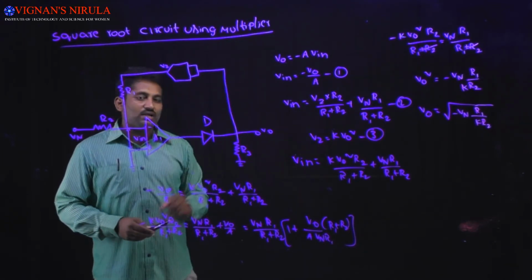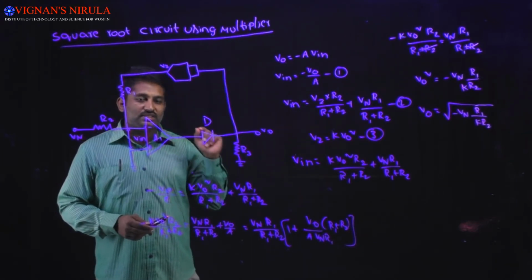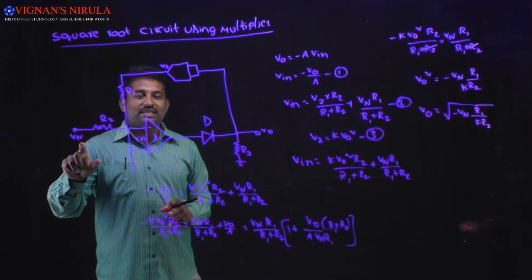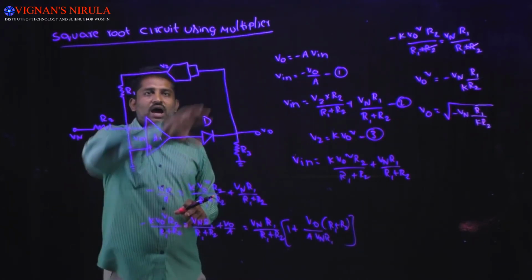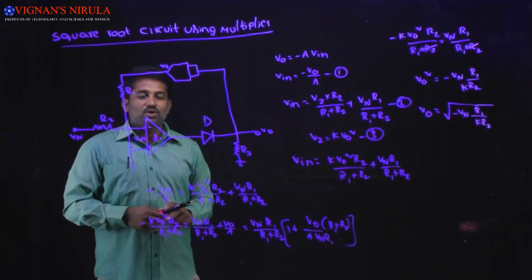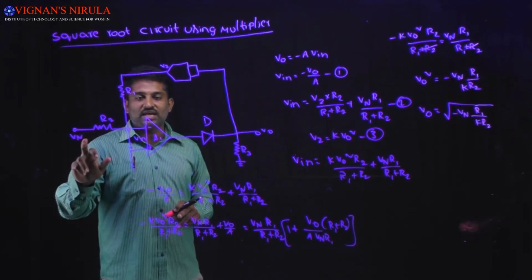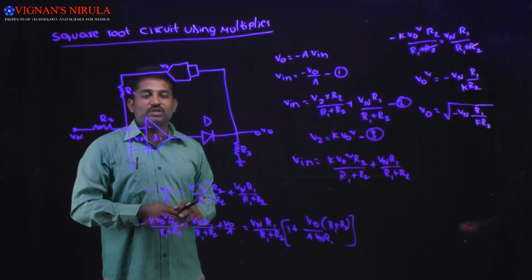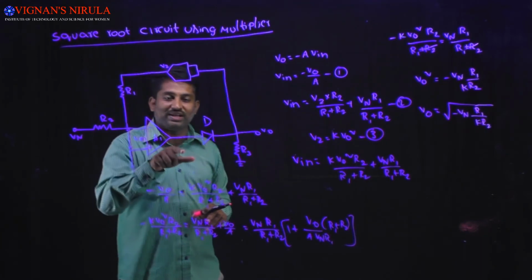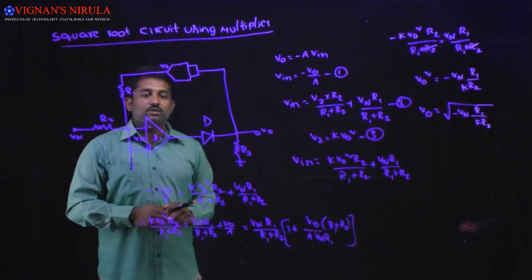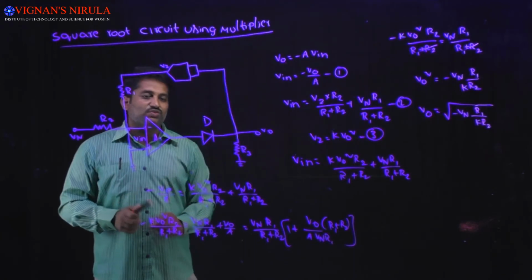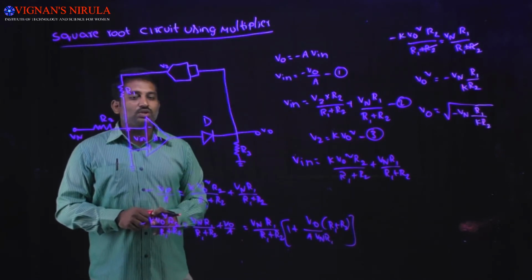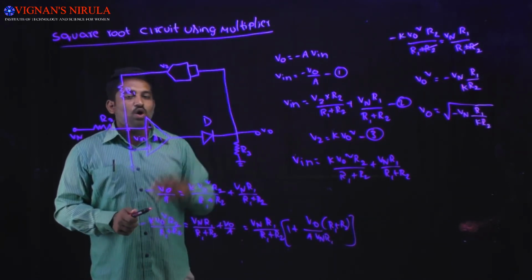An important point in this case is to always take Vn as a negative value, otherwise the circuit is latched up and it will break the feedback path. Why? Because if you take Vn as negative, because of the inverting configuration we get the output as a positive voltage. We get a 180 degrees phase shift with respect to the input, and otherwise it will act as a switch. So to avoid this we use a diode D connected in series with the output voltage.